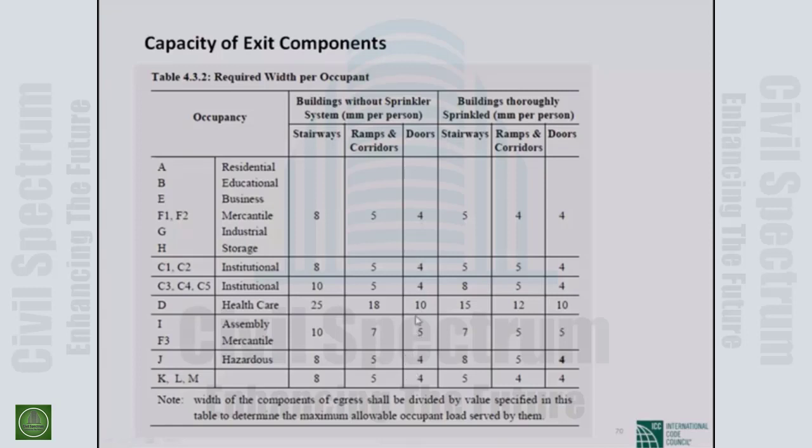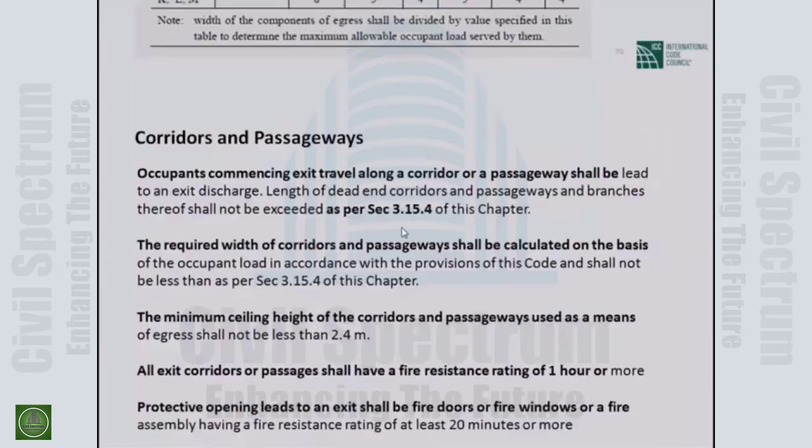It is almost double because if we consider the people coming from upstairs, a stair always has almost double the population than the level at the door, because from the door some people will go outside, and some will go to the stair. In the meantime, people from upstairs will come, so there will be many more. They need much more area. Normally, if we think about sequential evacuation, 2 floors will be coming at the same time. That's why it is considered almost double in different ways.